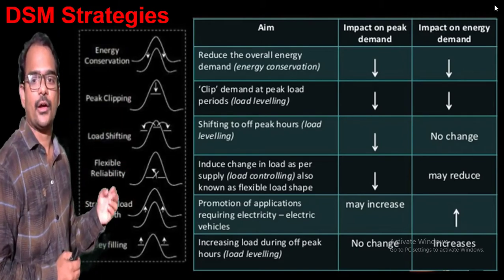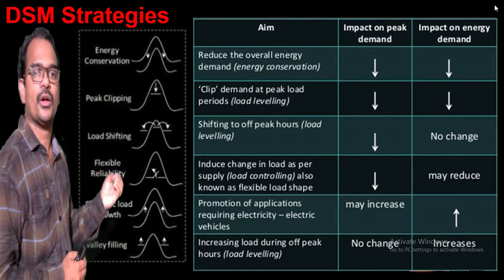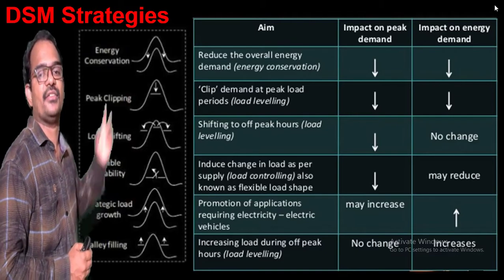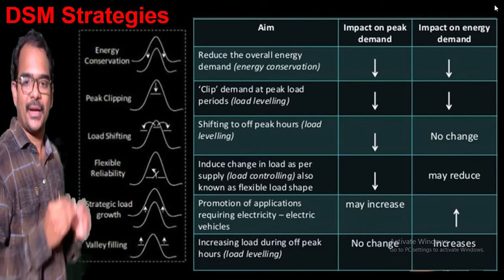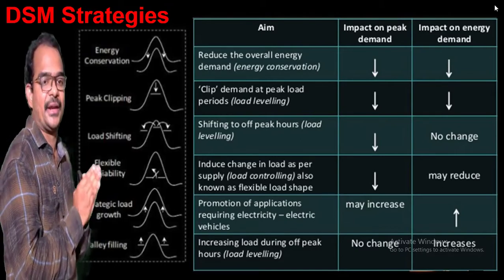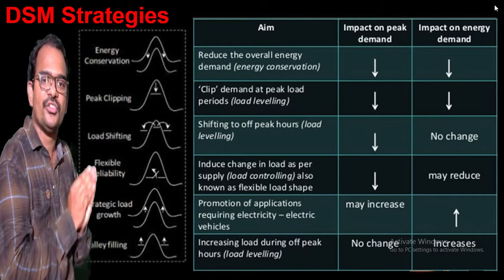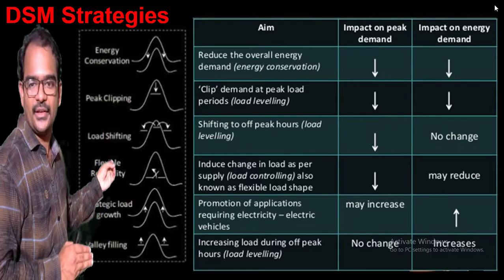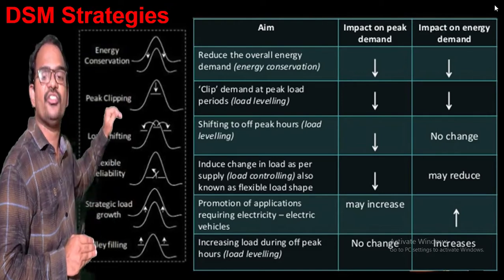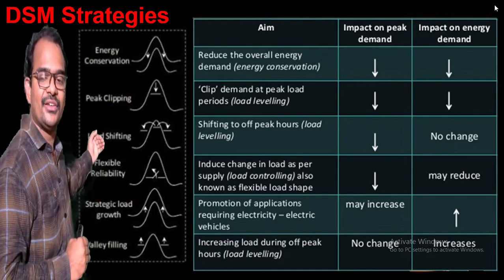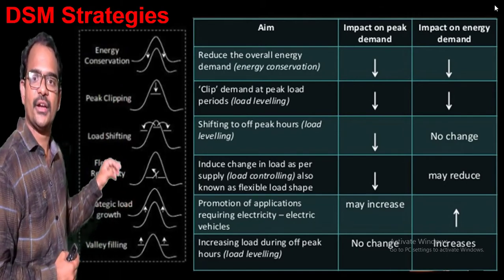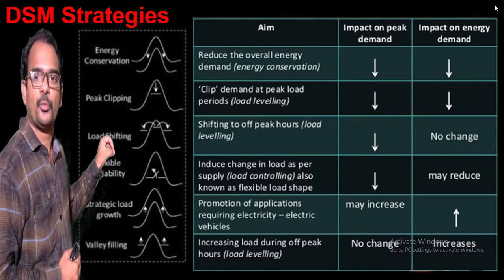And the fifth one is static load growth. By incorporating this technique, you are able to increase both the peak demand as well as the energy demand of that region. And valley filling, by implementing this technique in the region, you can observe a change only in the energy demand. The energy demand will increase, but there is no change in the peak demand, because this is the only technique where you are not bothering about your peak demand, you are bothering about increasing your off peak period energy consumption, and that's why your energy demand will increase, whereas for the peak demand there is no change. All these are the different demand side management or demand side response strategies.